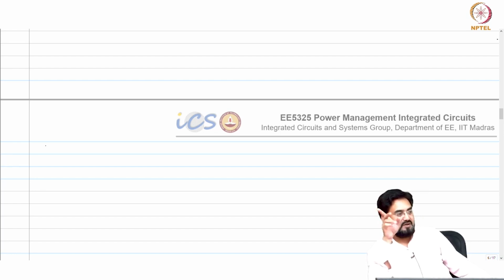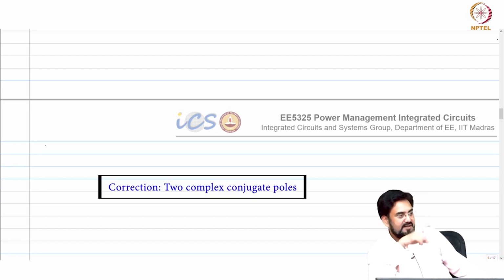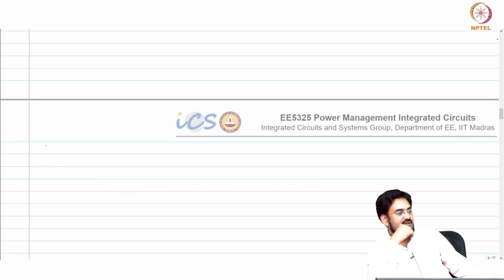If we had one more pole, let us say 2 real poles and 1 integrator, so 3 poles, and let us say we have one more real pole which is outside UGB. Okay. Then that pole will also contribute in the phase drop, because that is outside your UGB, but it will have some contribution, 10 degrees, 15 degrees, whatever, depending upon how far it is from your UGB.